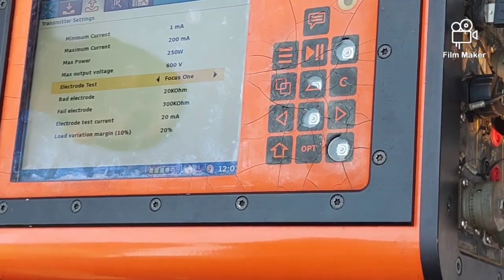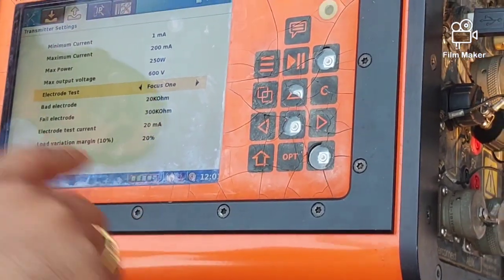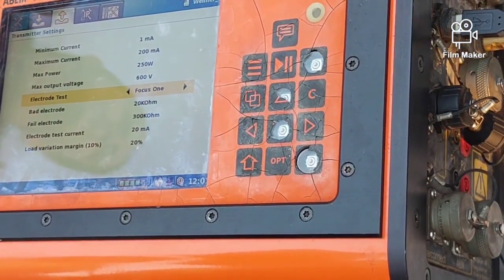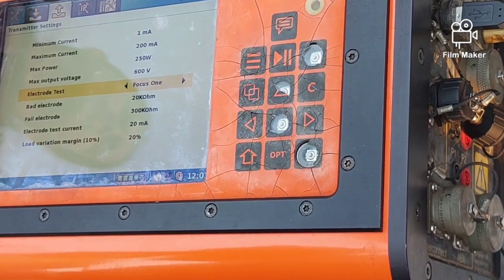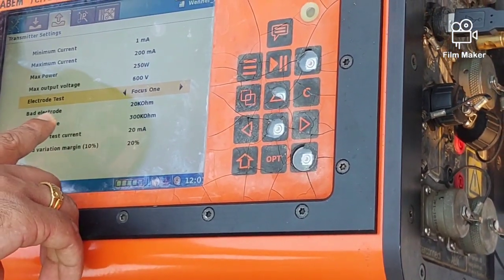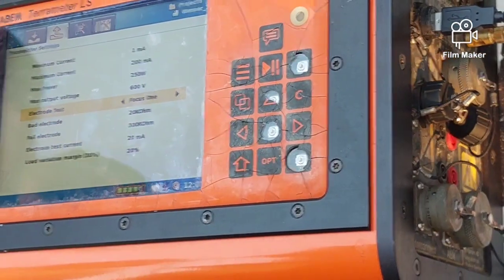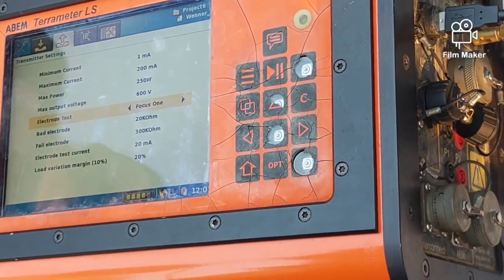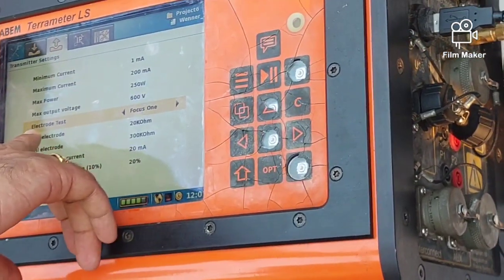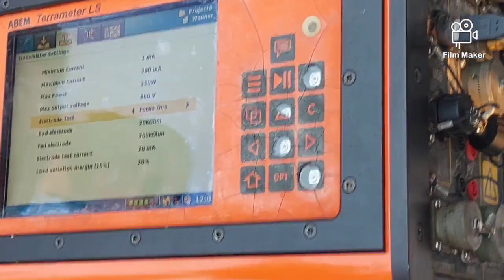Because we put some salt water, if that salt water is not enough, or it didn't connect to the wet layer of the earth, then it will show a bad electrode and the measurement will stop there. You have to put more water there and wet it to get it correct. So we are also on it, that is the electrode test. Okay, that is it.